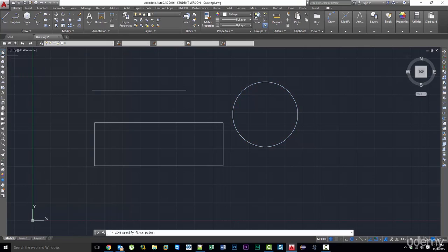So if I want to draw some lines between these quadrants, look, I get a diamond shape. So we have squares for endpoints, we have triangles for midpoints, we have circles for centers, and we have diamonds for quadrants. So they really went all out to give us a whole bunch of different shapes just so we don't get bored, and you got to appreciate that. So if I want to draw a square inscribed in this circle, that is not a problem. I can go from quadrant to quadrant, and look at that. It's beautiful. I'm getting more and more artistic as this course goes. I love it.